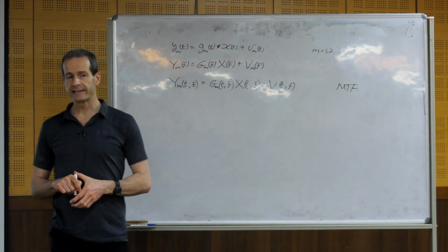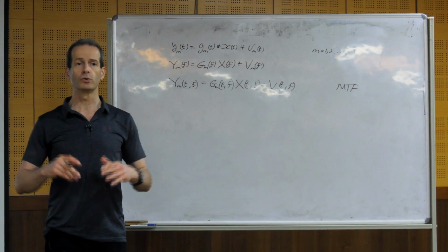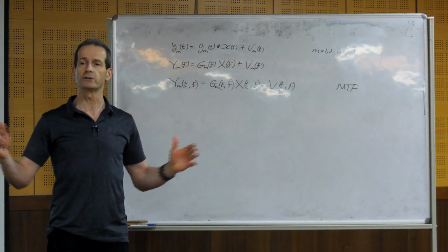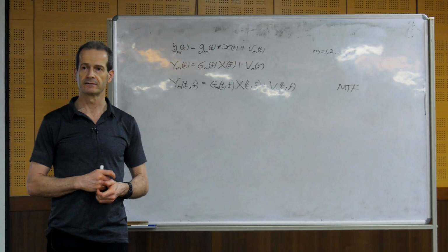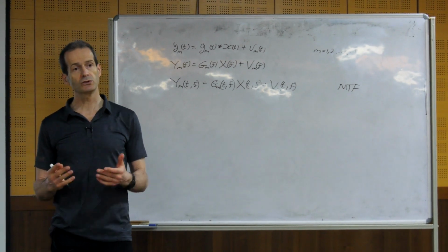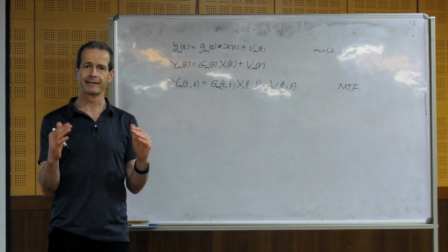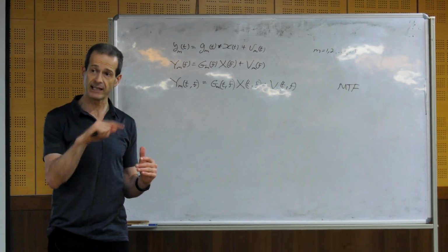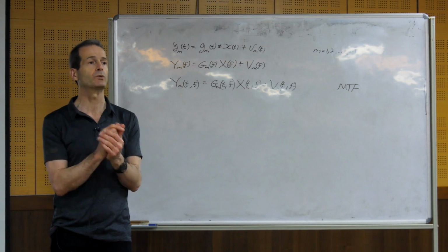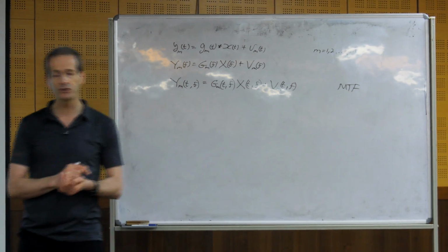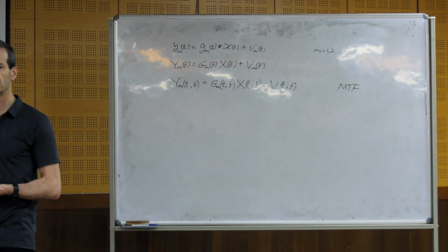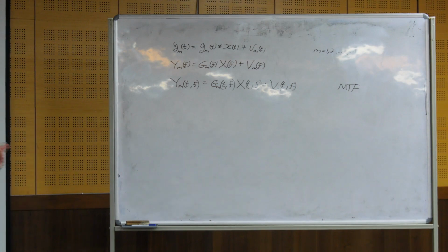So what we said is that sometimes you don't want to work with a long window in the STFT, because you want a window such that the signals can be approximated as stationary during that window. For example, for speech signals, we work roughly with 20, 30, 40, 50, and maybe sometimes 60 milliseconds.